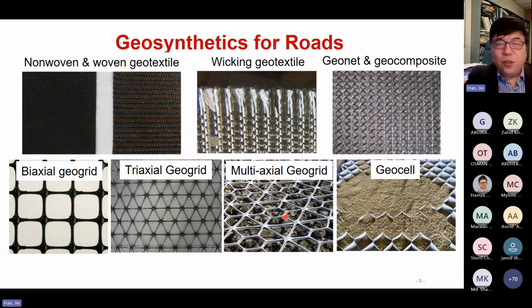Then this is a unique geogrid. Basically, there are 3 different shapes, 3 different sides. As you can see, this is one here, and another triangular here. Okay. Now, why produce 3 different shapes, sizes? Because we know that aggregate has gradation. That means the aggregate sizes are different in the mass of soil. If we have a different shape, different size, the particles will interlock better with those apertures.